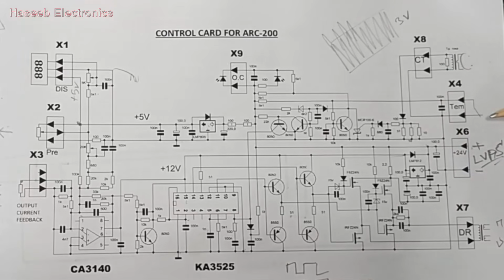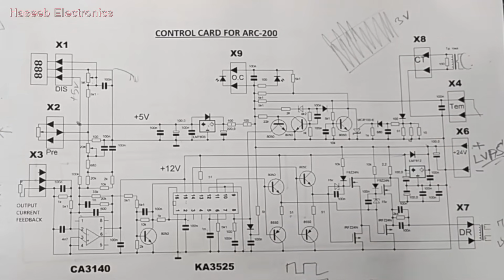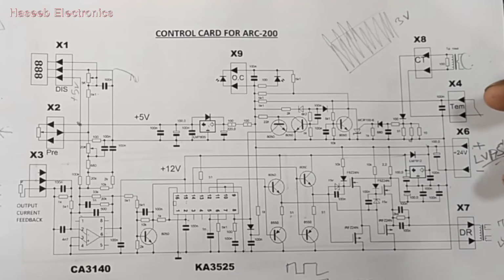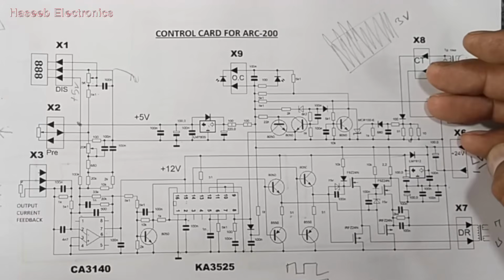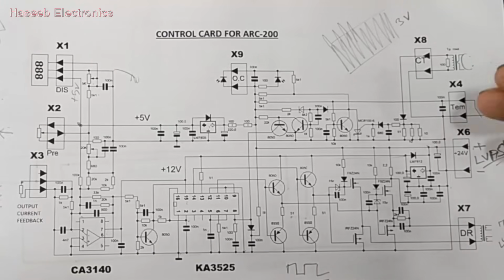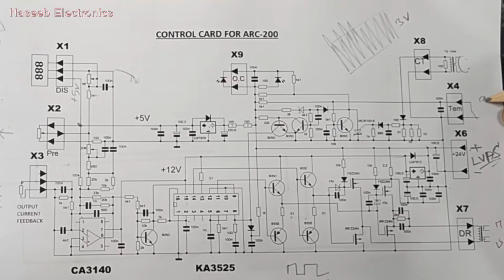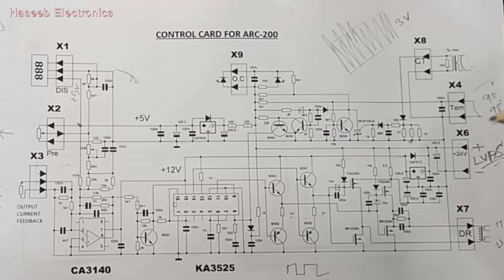The second thing, if our fan is choked, the duct is closed for the heatsink, or due to any reason the MOSFETs are dissipating heat, maybe we replaced some MOSFET with another type which has RDS more than the suggested value, it will dissipate more power. When it dissipates more power, the temperature sensor might be at 90 degree, 96 degree, 98 degree, whatever its category, it will switch.